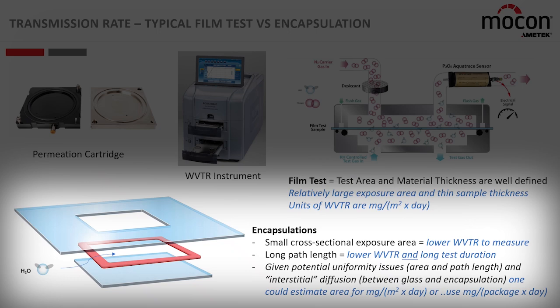Also, there might be some issues of uniformity. How well did I put the sealant down? Is it really a uniform thickness throughout? Is my width good? Is my thickness uniform? All that neat stuff. So if I can't put it down in a uniform manner, taking the data in place and trying to understand how to work with it could be kind of challenging.